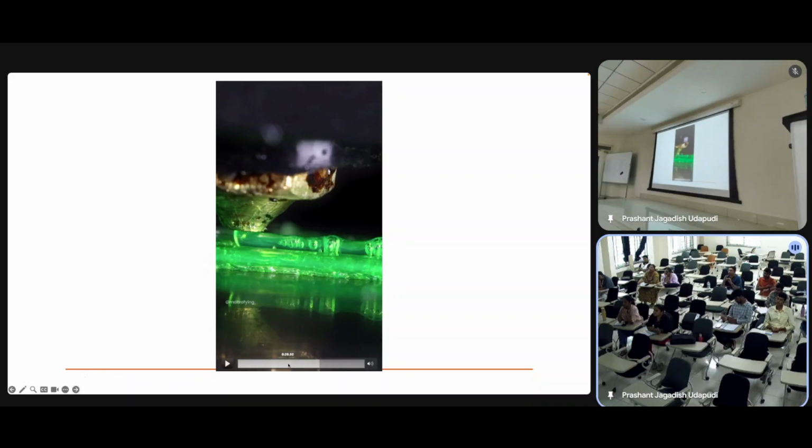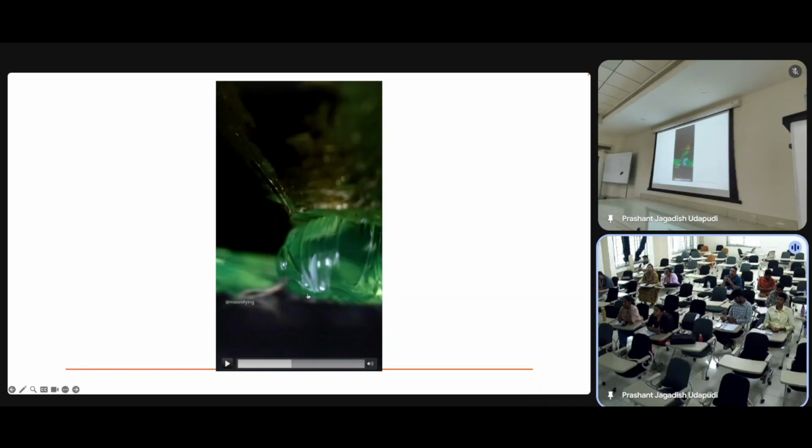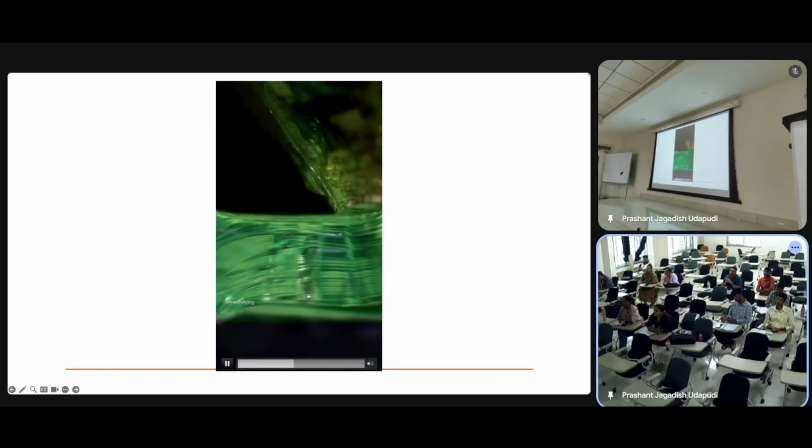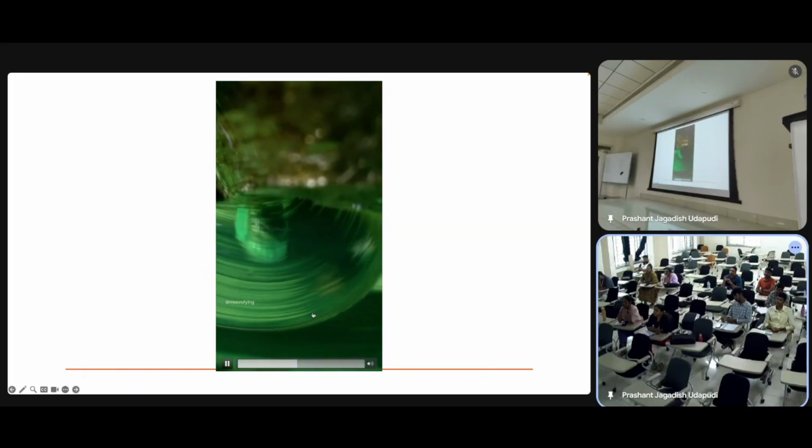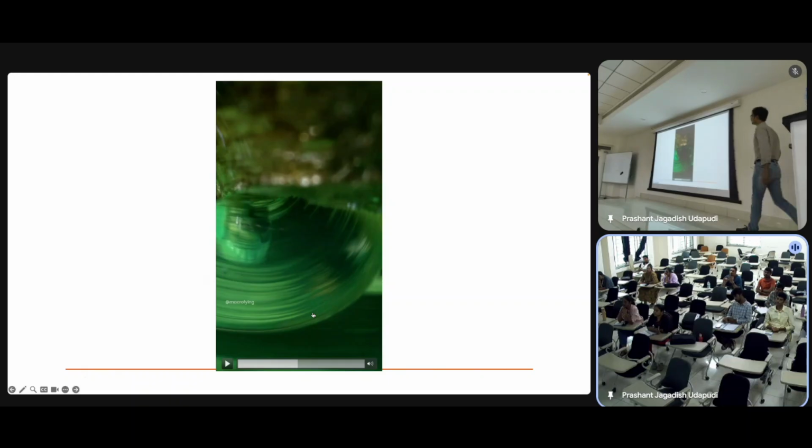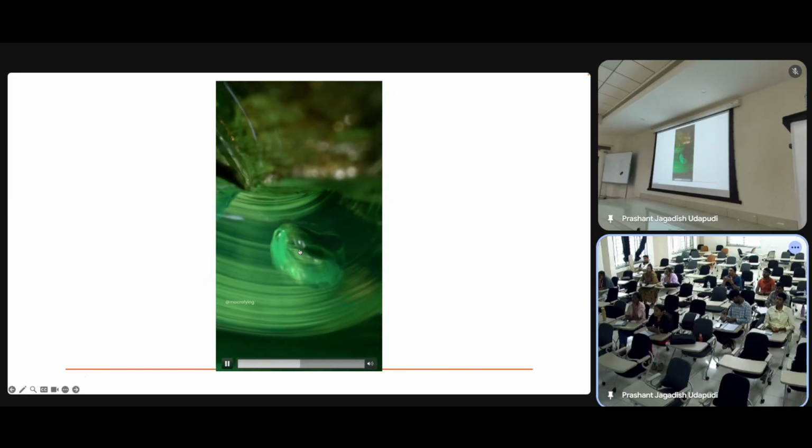And then we found, when you see the closer look, this is very common. This is even coming from the nozzle. This is where a big air bubble is coming through the nozzle even after forming, and it also depends on the solidification, based on the environment temperature. So this will further create a bigger problem.